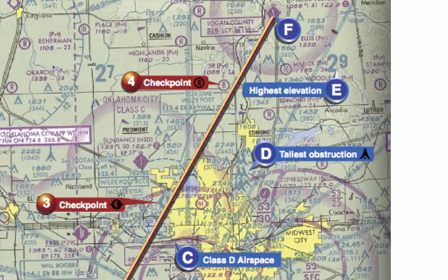This altitude also gives adequate clearance of all obstructions as well as conforms to the 14 CFR Part 91 requirements to fly at an altitude of odd 1,000 plus 500 feet when on a magnetic course between 0 and 179 degrees.